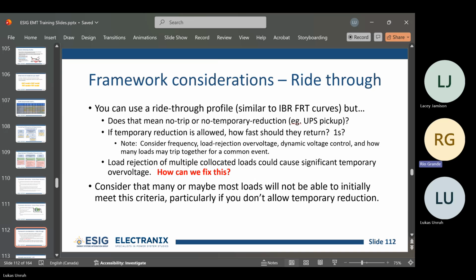But right now, the IVR ride-through in PRC-029, actually 2000, is well outside the synchronous machine trip setting. So that is a great place to start, and it probably gives us margin until we're at, I don't know, 70+% penetration of IVRs all the time. Random number I picked. So you certainly could, but is it worth it? Do you get more benefit just having the collaborative discussion?